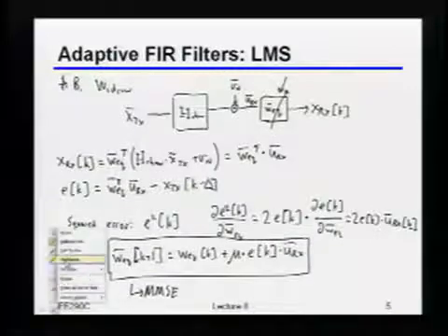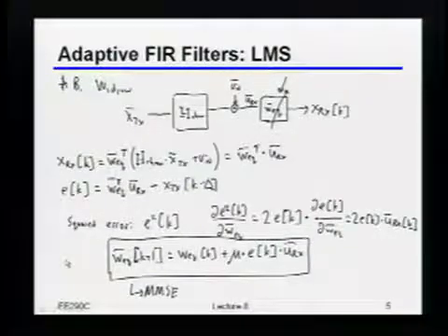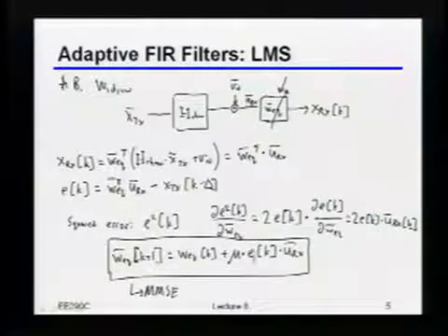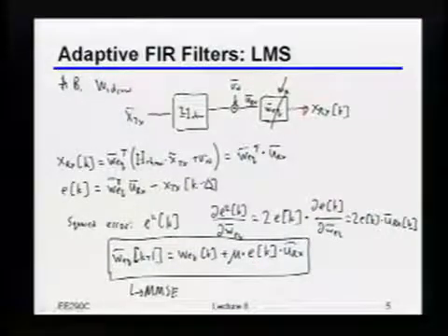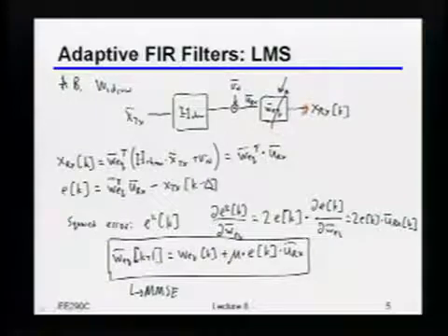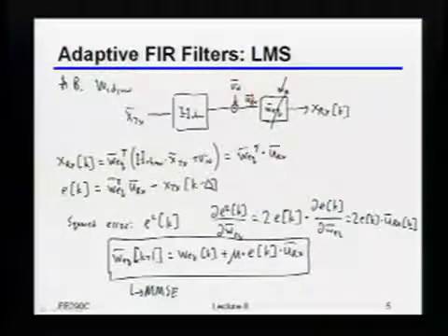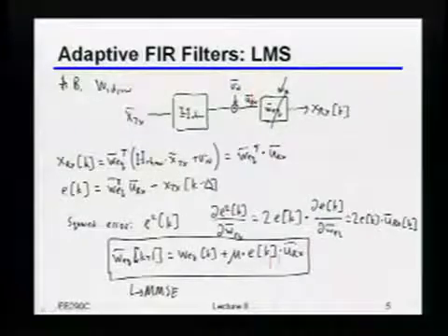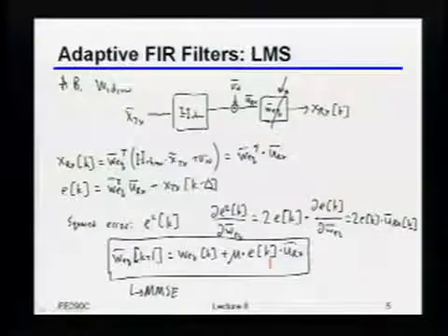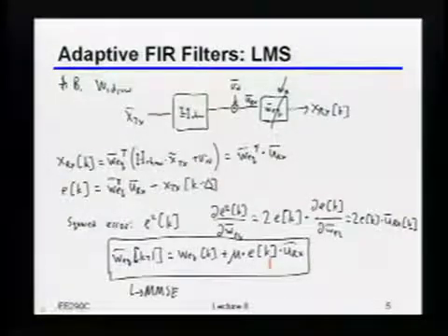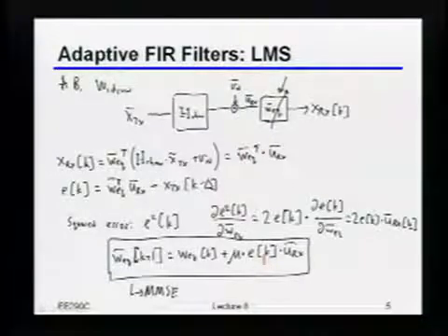Okay, and just intuitively, this is actually a good thing to notice. Notice that what I'm correlating is the error at the output over here, which is after the equalizer, with the input to the equalizer. Okay? That input contains the noise, right? So another way of interpreting this, if you think back to your statistics, whenever you multiply things and average them, that's like doing a correlation, right? What you're doing here is driving the correlation between the error and the input to the equalizer to be 0.